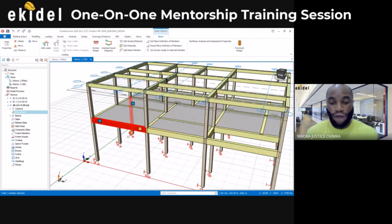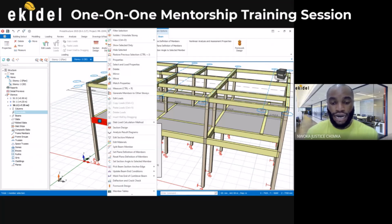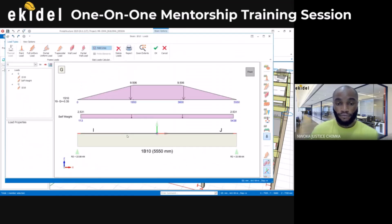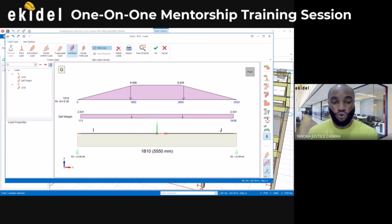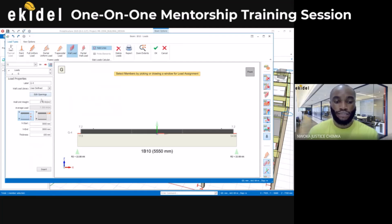So by doing that, I'll right click, just click on any of the beams, then right click, and then you will see it says edit loads. I will then click on this here, then wait for a while for the dialog box to display. Okay, now here we have several loads: point load, uniform load, partial, but we are dealing with what? Wall load. So I'll come now and click on wall load. Now it will display this load with properties and all that.